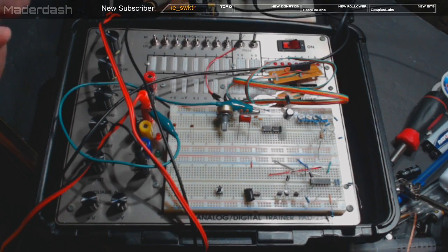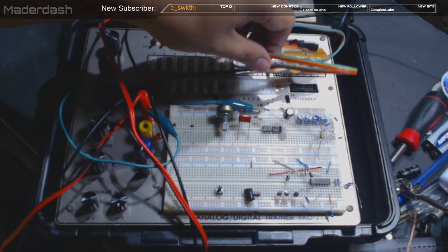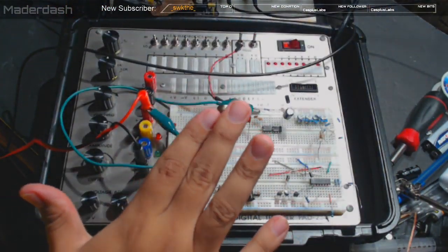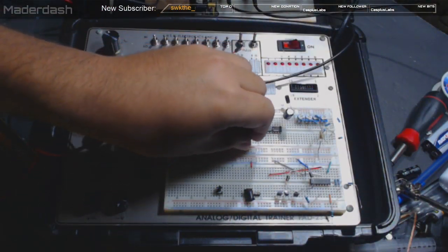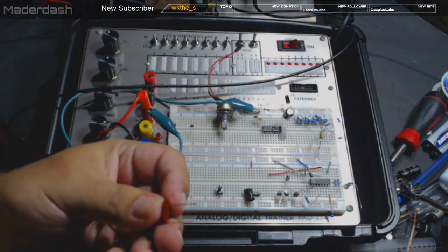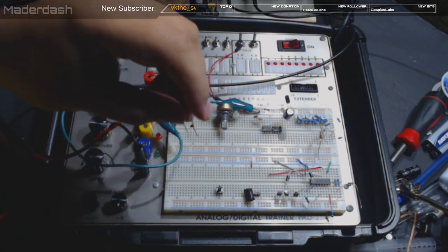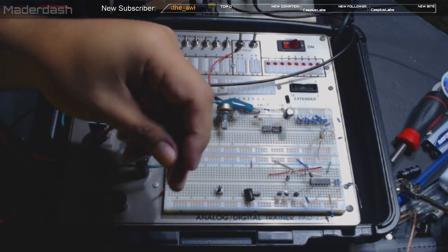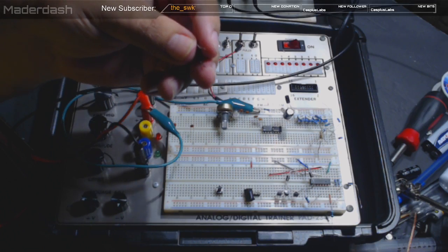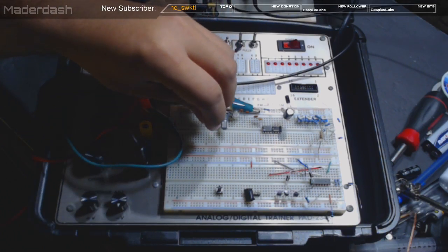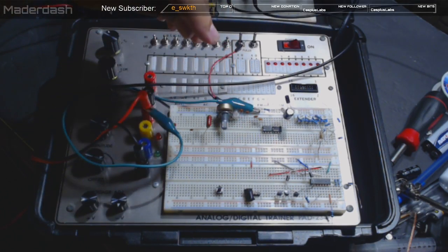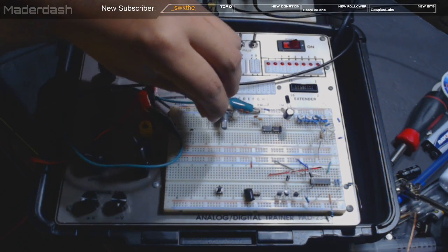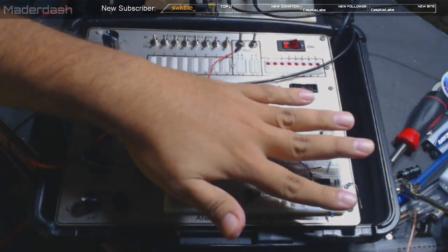Oh wow, it has all kinds of functionality in it. That's cool. You have a breadboard, which is used if you have small components like a capacitor or resistor, but you're just testing stuff out. You don't know exactly how you want the circuit, or exactly if this is the capacitor you want or a larger one or a smaller one. You can test stuff out in it. You could try that capacitor, no, that ain't the one I want, or I don't want it on that pin, I want it on a different pin. You can just swap things out. So that's the purpose of the breadboard.